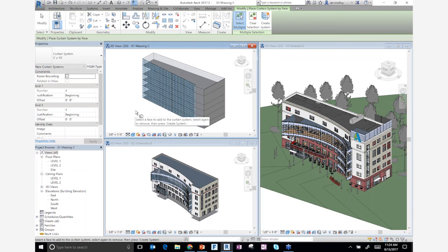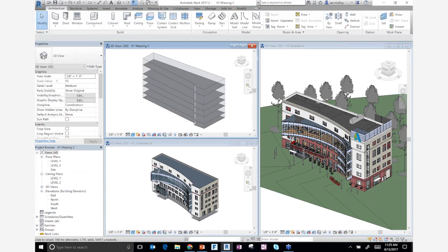And in energy modeling terms, this level of detail of a building is more than what an energy simulation really needs. And you can very quickly start to represent it in this form. What we've got, of course, in Revit that supports Insight is the ability to automatically create an energy model from any Revit model, meaning we can go from conceptual all the way through to detailed. And because we're using the one model, we can track energy consistently throughout all phases in the design process.